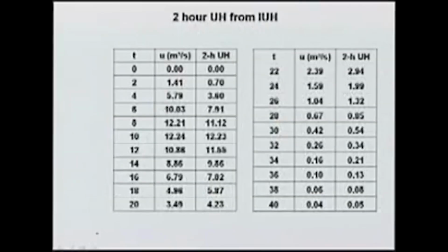So, here we would look at some uses of this IUH. Suppose we are given the IUH and we want a 2-hour unit hydrograph derived from the IUH.